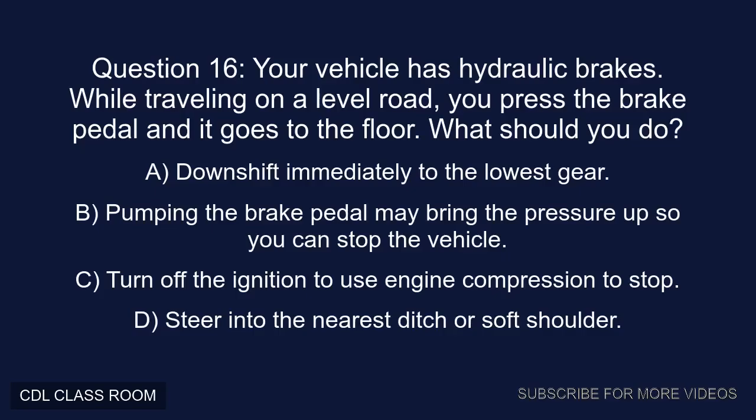Question 16. Your vehicle has hydraulic brakes. While traveling on a level road, you press the brake pedal and it goes to the floor. What should you do? A. Downshift immediately to the lowest gear. B. Pumping the brake pedal may bring the pressure up so you can stop the vehicle. C. Turn off the ignition to use engine compression to stop. D. Steer into the nearest ditch or soft shoulder. Correct answer, B. Pumping the brake pedal may bring the pressure up so you can stop the vehicle.